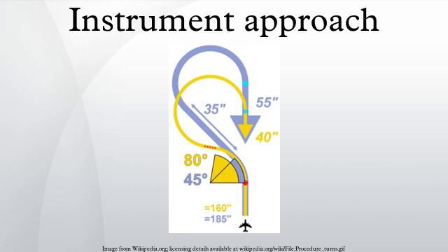When an aircraft is under radar control, air traffic control may replace some or all of these phases of the approach with radar vectors to allow traffic levels to be increased over that which is possible when following the full procedures. It is very common for ATC to vector aircraft to intercept the final approach nav's course, for example the ILS, which is then used for the final approach. In the case of the rarely used ground-controlled approach, the instrumentation is on the ground and monitored by a controller, who then relays precise instructions for adjustment of heading and altitude to the pilot and the approaching aircraft.